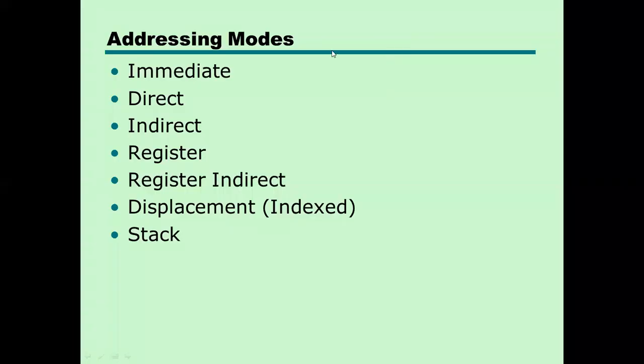So when we talk about the addressing modes, the definition of addressing mode is the way in which the microcontroller handles the information or data from the memory or the peripheral devices. So on the basis of where the data is being addressed from, the addressing modes are classified as immediate addressing mode, direct addressing mode, indirect addressing mode, register indirect, then there is a displacement addressing mode and stack related addressing mode. Okay, so we'll see that one by one.